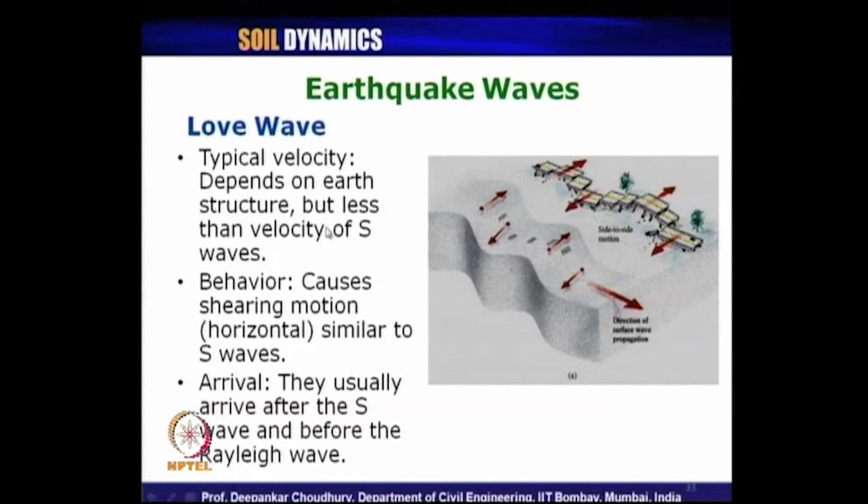So, you can see depending on the velocity of shear wave, love wave and Rayleigh wave, their recording times, the time difference between recording of shear, love and Rayleigh wave in the seismogram, is hardly any difference. They almost come one after another. So, S wave, soon after that love wave, soon after that Rayleigh wave. That way it is getting recorded in the seismogram, whereas there is a substantial amount of difference between the P wave and S wave arriving at the seismogram.